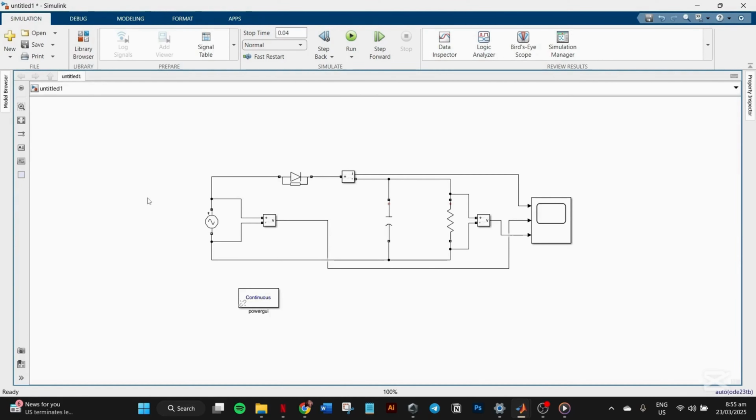Here's where the capacitor filter, or the capacitor, comes into play. It's connected parallel to the resistive load and does an amazing job at smoothing out the signal. When the diode is on, the capacitor charges up to the peak voltage. As the input voltage starts decreasing, the capacitor gradually discharges, providing a more stable DC output. The resistive load, or the resistor, receives this filtered DC signal, which is much smoother than the original pulsating DC.